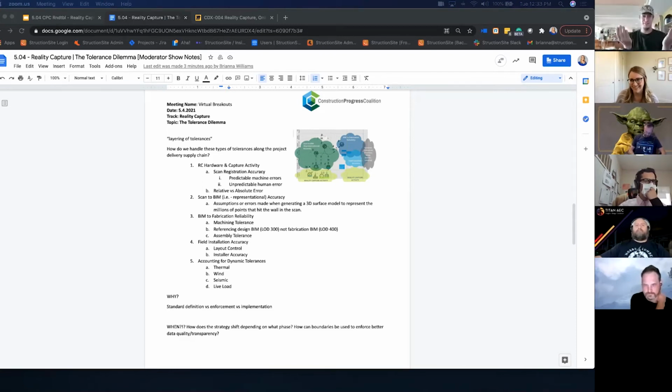And then people look at spec sheets and say, well, the point accuracy of this is this, and the range noise on the BLK is this, and it's less. And we're like, yeah, but the point accuracy of the BLK is like 3 times worse because the rotational measurements are also 3 times worse. Wow.